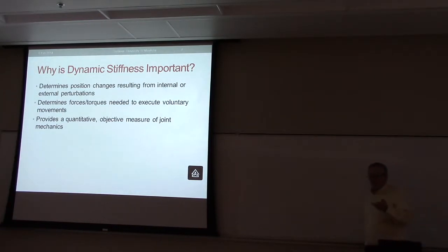If I go to my neurologist and complain that I have a stiff joint, he's going to move my limb back and forth and say possibly you're normal, you're hypertonic, you've got more resistance, or hypotonic, less resistance, and if it's really bad, he'll say it's plus plus or plus minus. Basically, he's working with about 5 different levels. He's working with a 2-bit A to D converter. Since A to D converters basically have 1 bit of noise, what you're looking at is they can tell hyper and hypo from normal, but it's not a very sensitive measure. And as we'll see later, it has some other issues.